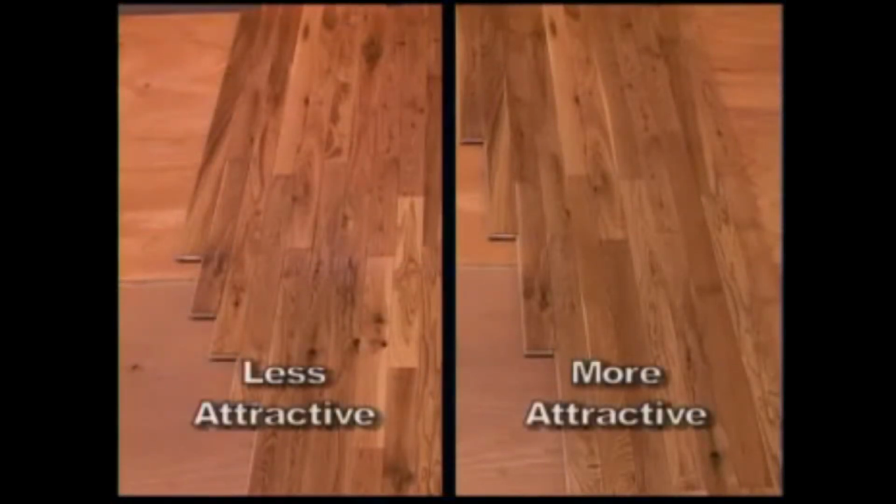Inspection of the wood, randomly staggering the lengths, and sorting or cutting away unattractive areas all contribute to the desired intentional randomness appearance. Mix 3 or more cartons together during installation and scatter extremely light or dark boards. Intentional randomness allows the wood to look its best and eliminates undesirable visual clusters.